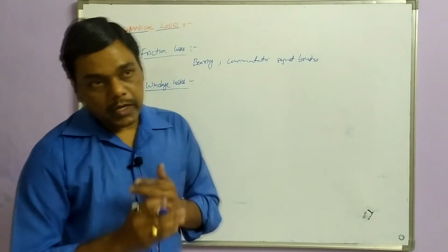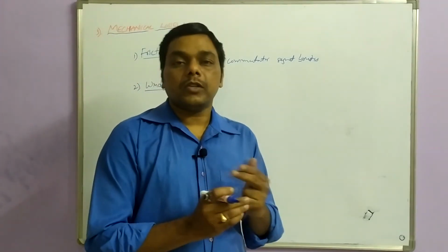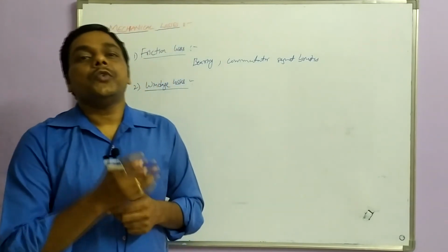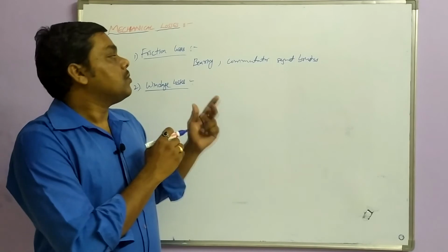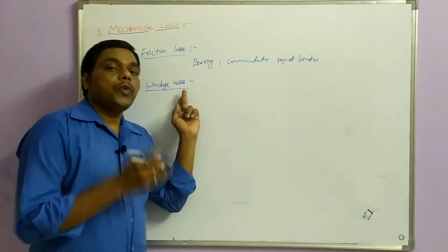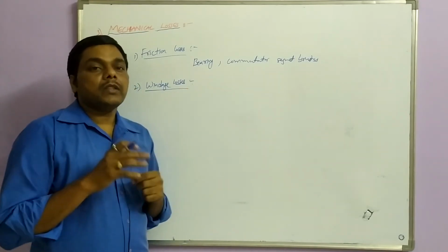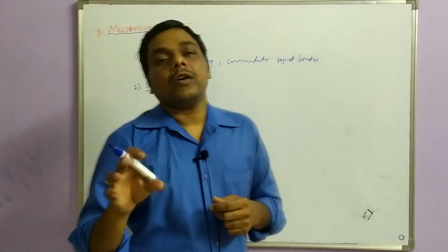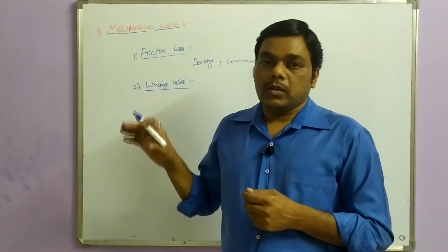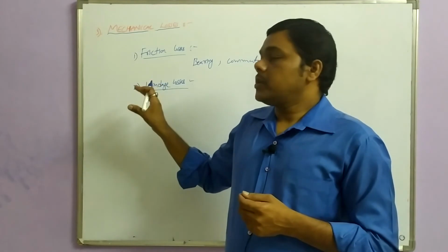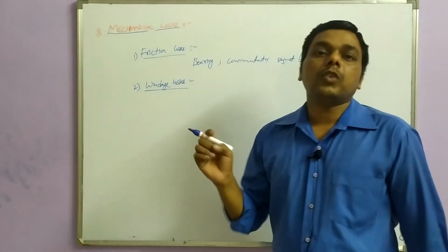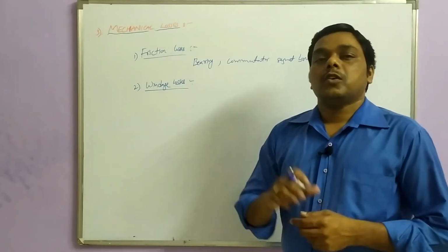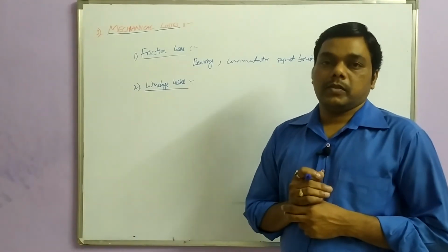Or in the opposite direction, if the motor or generator is rotating, due to that air resistance the speed of your shaft is going to decrease. We provide ventilating ducts in the armature through the end cover and armature core, so the air flows into the generator to cool the armature.